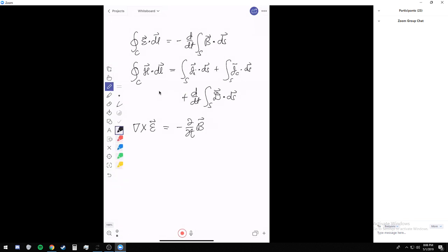Okay, so now the corresponding term for the second one is curl of H equal to basically impressed current density plus the conduction current density plus partial derivative, again we assume that the system is stationary, right, of D. Now I do not put the dependency now. So this term is nothing but sigma E, right? Let me write down, this is nothing but sigma times E. All right, so this is general time variation. So this is basically the focus of 6, 7, and 8, and so on.